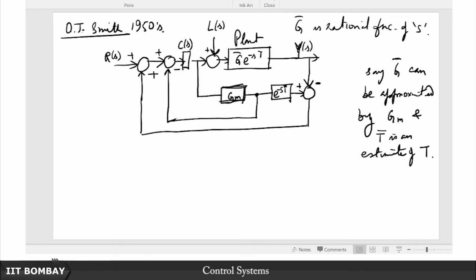So here's what I do. Okay. So that is the complete structure of the Smith predictor, right, where we have the actual plant, we have a model. So remember, this is something that we are designing by a piece of code, this is something we are designing by a piece of code, and this is also something we are designing by a piece of code. Only thing, over these we do not have any control. Whatever is best for the plant, whatever is the best approximation of the plant, we just pick those parameters here in these two. But this controller is in our hands. We can make this a P, PI or PID controller as we discussed in the previous lecture, right.